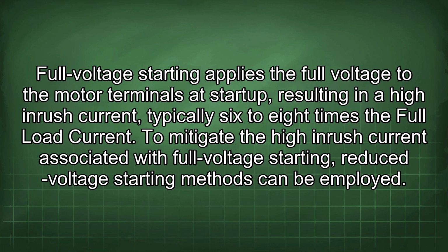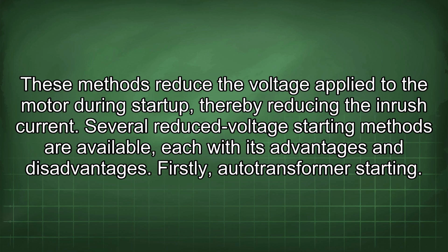To mitigate the high inrush current associated with full voltage starting, reduced voltage starting methods can be employed. These methods reduce the voltage applied to the motor during startup, thereby reducing the inrush current. Several reduced voltage starting methods are available, each with its advantages and disadvantages.